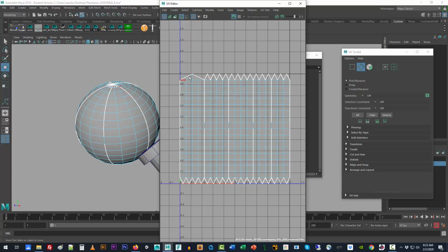and then go to Cut and Sew and sew them all together at once. And what that's going to do is create a singular point, which, if this is going to be one of the little orange slices, you merge them all together so it's a little easier to do. So we just go along the rest of these edges and grab them as they belong to each set. In fact, I think I can do just one big selection like so.